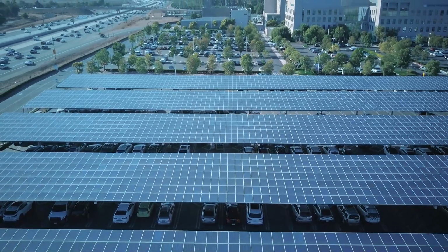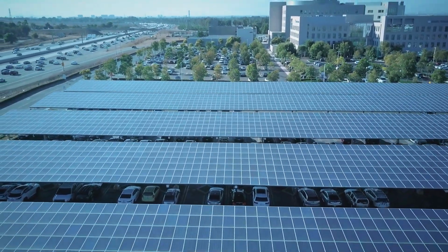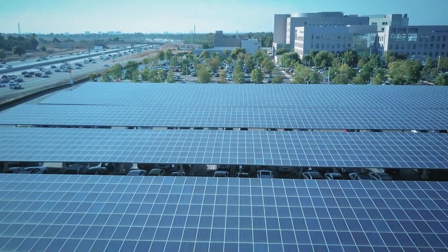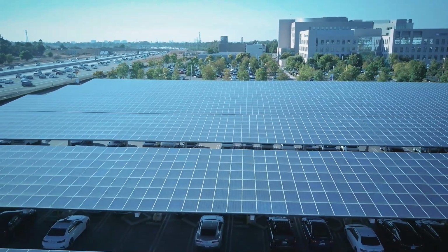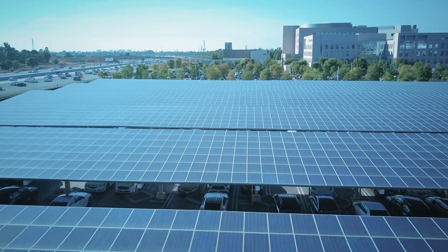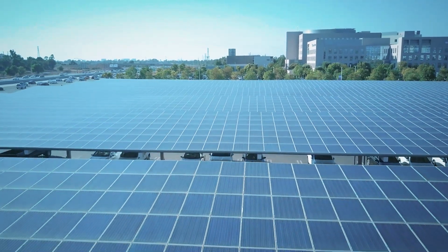You need to connect them to balance the solar system to maximize the input without exceeding the maximum capacity of the power station or solar generator. Often, you need to connect multiple solar panels to a single power station. The way the panels are connected to each other and the balance of the system affects how efficiently the solar array captures and stores energy.